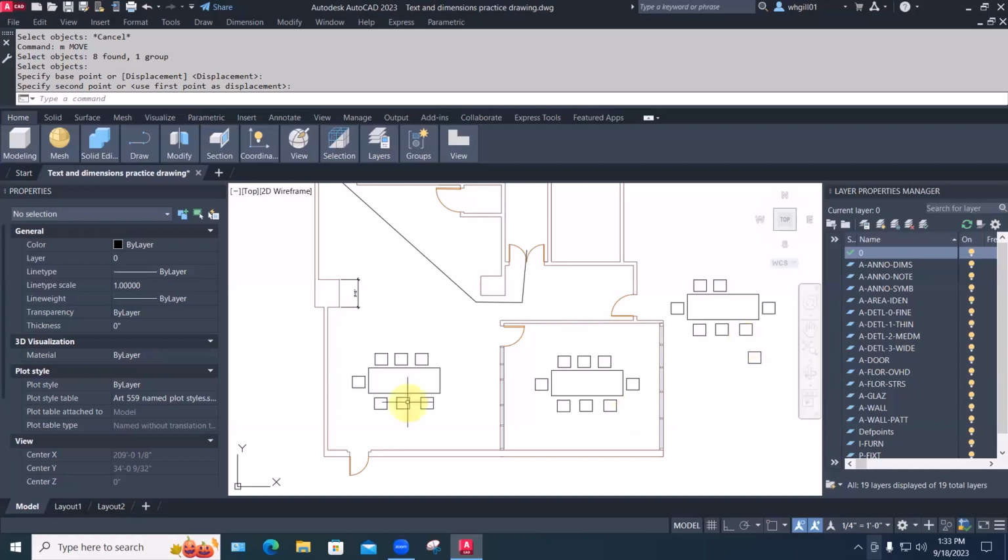It's quite a different story for blocks. Unlike groups, which are informal and can come and go, and you can sort of add and subtract pieces and they don't change each other, blocks are usually just one thing, like a bathtub or a chair or an ashtray or a light fixture, something related to one discipline and not something we're just going to mess with randomly. So as an in-house exercise, let's go ahead and make an actual chair as a block and place it, make copies of it, edit it, and watch them all change at the same time, so we can get some idea of how we can make the auto part of AutoCAD start to do some work for us instead of drawing things over and over and over again.